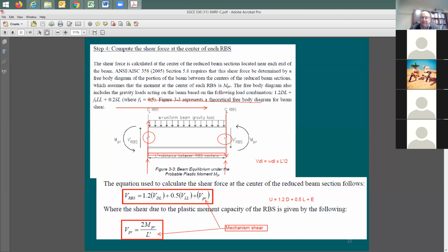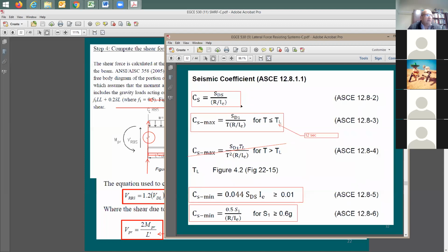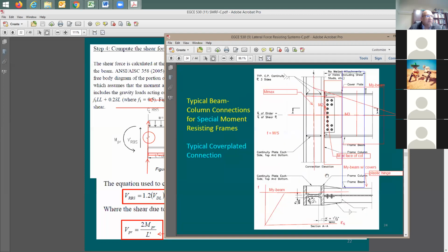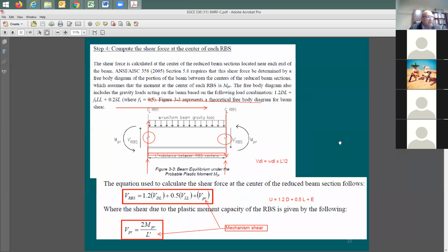The seismic forces that we have been talking about are based on our seismic analysis, based on the mass of the building, based on the initial period of the building, based on all of this analysis that you are going to be doing. With this, you obtain some seismic forces, you put them in the moment frame, then you solve the moment frame and you get some moment and some shear. Like in here. This shear here is completely different.